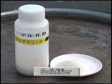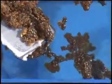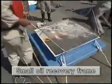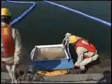Solidifiers are used to make oil solid. After they are spread over the oil, the surface of the oil slick is agitated slightly to make them more effective. Once the oil has become solid, it can be scooped up using a small mesh wire net. There is also an oil recovery frame. After the oil spill has been gathered and transferred into the frame, the oil slick itself will thicken in the frame and can be recovered.